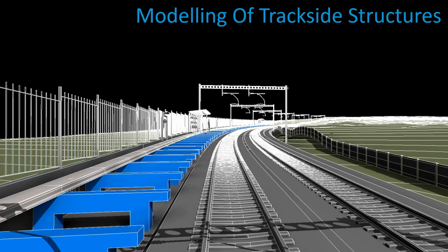Now, all of this system is a precast system, and we've used the Dynamo script here to actually place out these precast members. These have been modelled in Revit as beams, so they have analytical models. And of course, with a beam, it can be placed down by a line rather than 2 points. So we're actually letting Dynamo place these across lines.